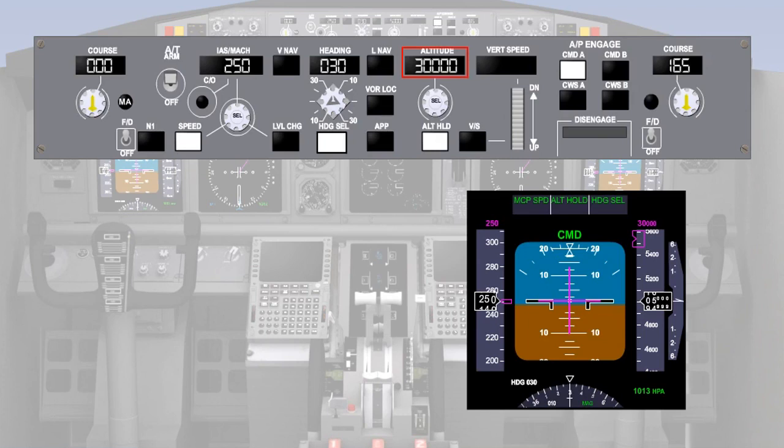So let's now look at vertical speed mode. The first action is to select the required altitude in the altitude window. This will arm the altitude alert system and also cause the autothrottle computer to calculate a value of climb thrust based on the altitude change. We are going to bypass the thrust computer and use vertical speed mode first.